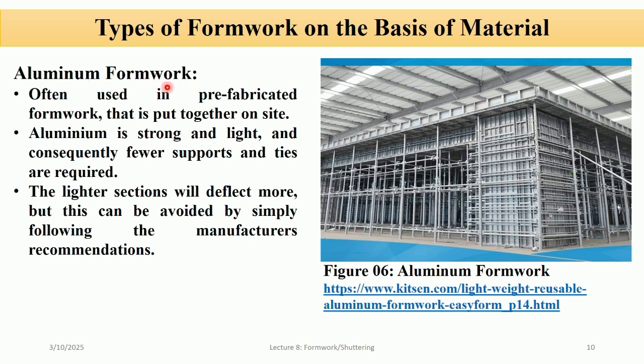Aluminium formwork. So it is a type of formwork made from aluminium alloy, a lightweight and corrosion resistant metal. The purpose of providing aluminium formwork is that it provides a smooth finish like plywood formwork. It supports the concrete, achieves accurate shape, and reduces the construction time.